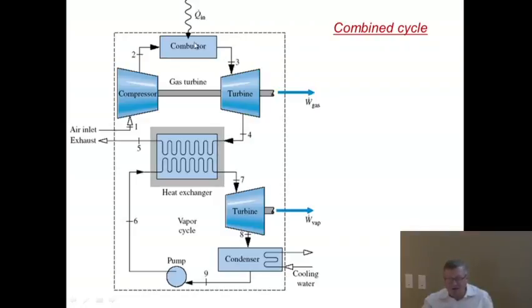It's much less than it would be if you used the combustion process directly to heat water, because this point here is at 500 or so degrees centigrade, 700 Kelvin. So you're better off using your gases, which are 2000 Kelvin, to heat a 1500 Kelvin point than to heat a 700 or 800 Kelvin point. That's why this is then the topping cycle.